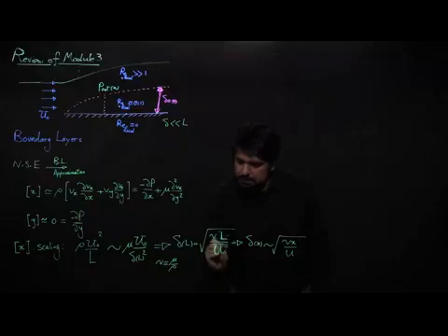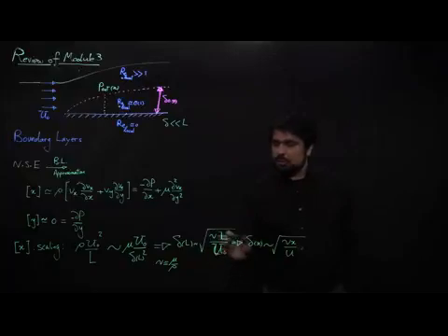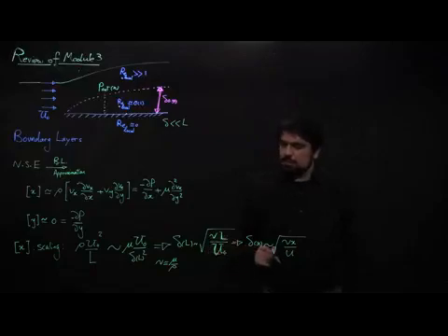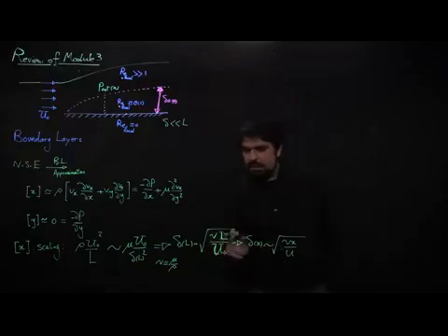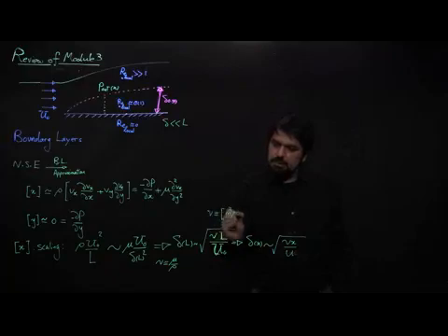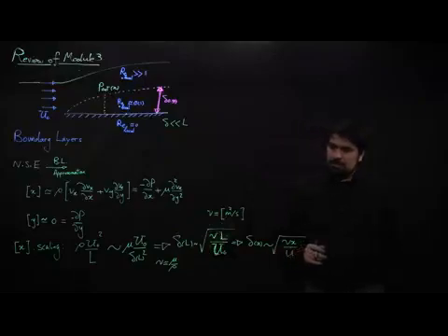And how I noticed this mistake is because nu should be multiplied by something that has dimension time. So length divided by u0 will give me time. That's the mistake that I made in the algebra there. So to correct it, it will be nu multiplied by length divided by u0, which is velocity, and the square root of that. Length is meter, u0 is meter over second. Meter divided by meter over second gives me second. The dimension for kinematic viscosity is area per second. Area per second multiplied by second will be area. A square root of that will give me meter.